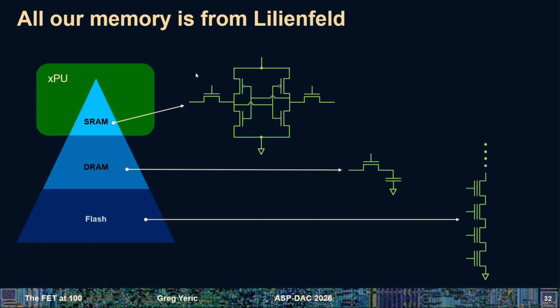So, talking about the SRAM from a top-down view, this is the circuit representation. You have this vertical connection, this gate shape that we saw before. That's going to be the word line to both of these pass gates. They're passing the signal in and out. And then there's a PN combination, what we call cross-coupled to each other.